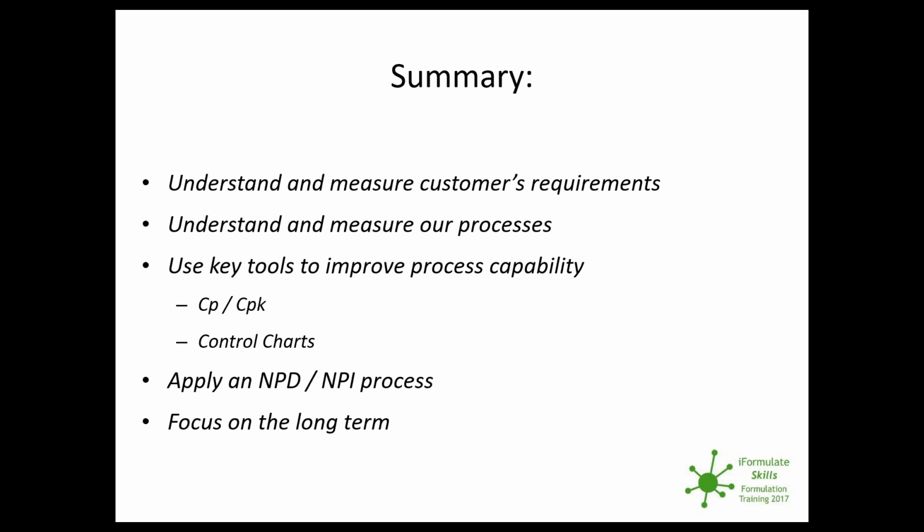Voice of the customer, we need to understand it, and we need to understand it in clear specifics. We need to be understanding and measuring our processes so that we can see the amount of variability that we get in our processes, and the key tools we want to be using are process capability measures, Cp and Cpk, and control charts to help us see the drift of our processes.